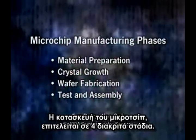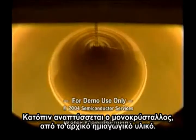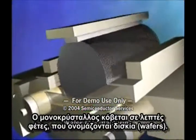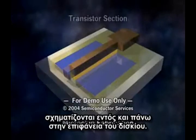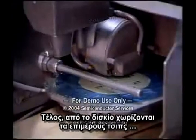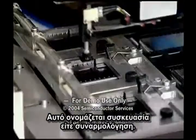Microchip manufacturing is divided into 4 distinct stages. Stage 1, material preparation, extracts and purifies the semiconducting material. Next comes the growing of crystals from the semiconducting material and preparation of thin discs called wafers. In Stage 3, microchip fabrication, the circuit components are formed in and on the wafer surface. Finally, the wafer is separated into individual chips, also called die, and placed in protective packages. This is called packaging or assembly.